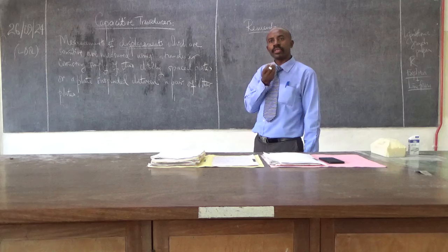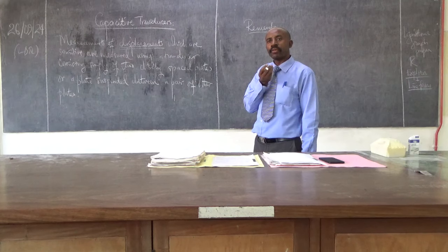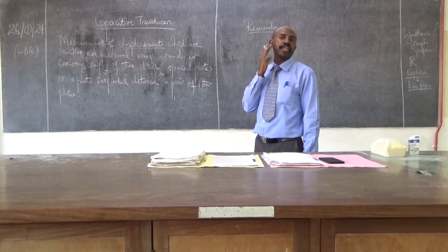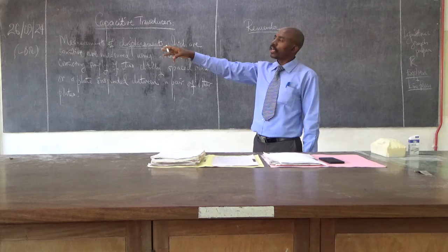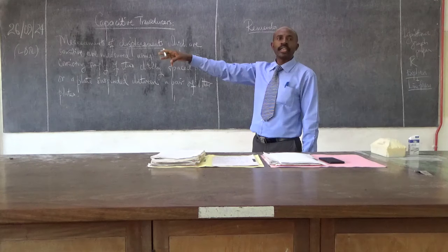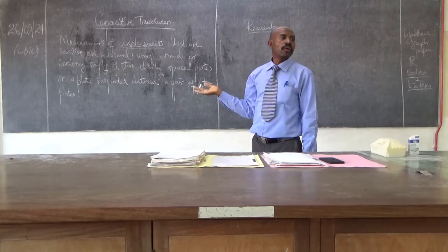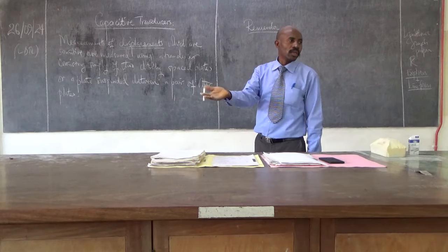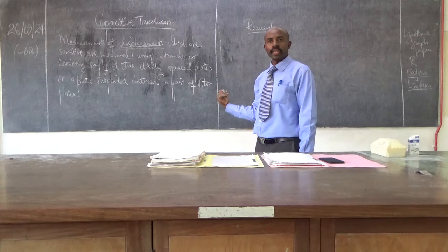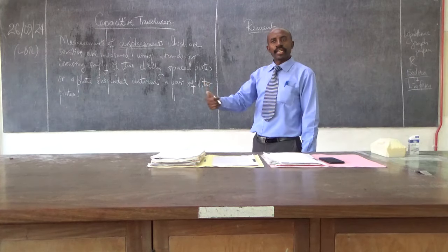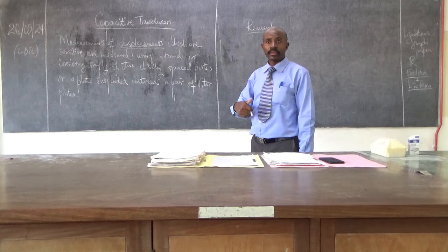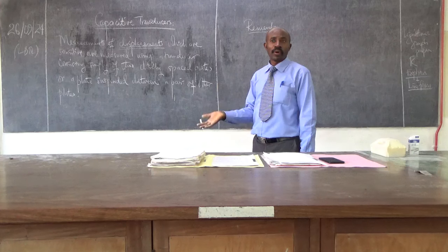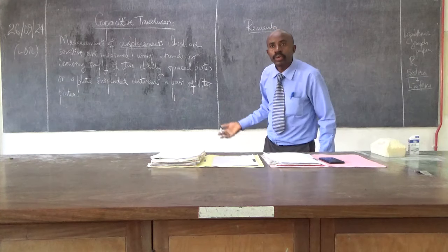They have a direction sensor for motion, then an LDR somewhere in the sides. So if you install it on a veranda, like on a shed, during the day, they don't go on, no matter the motion, even if they are on by the switch. If it is at night, they don't go on until somebody moves around. So they save power. They are only for security. It is until somebody comes in.